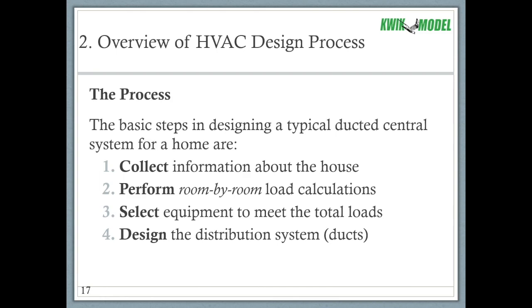You can't just have the direction it's facing. You have to know the number of windows, the type of walls, and all that kind of stuff. The next step then, once you have all that information, you perform room by room load calculations.